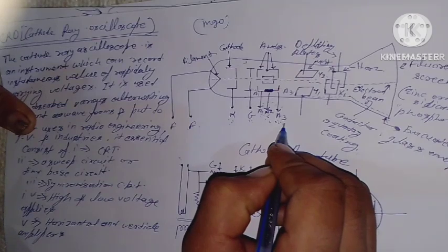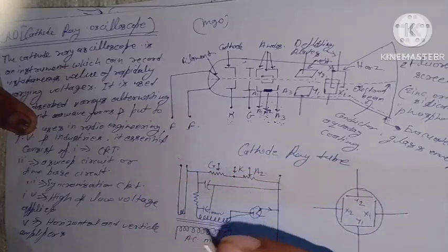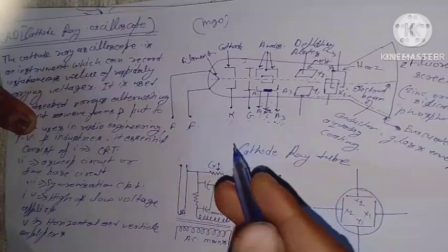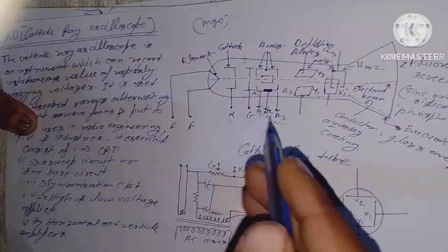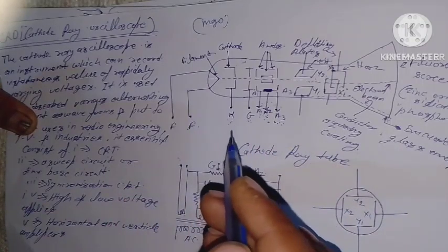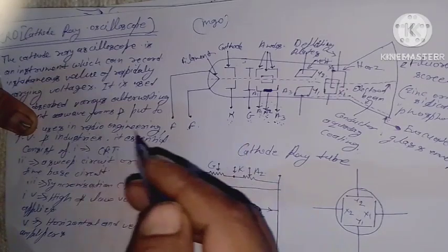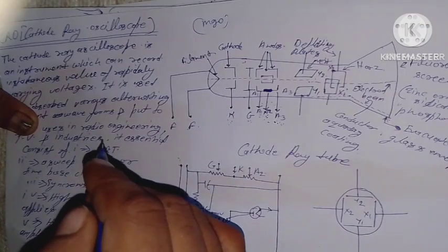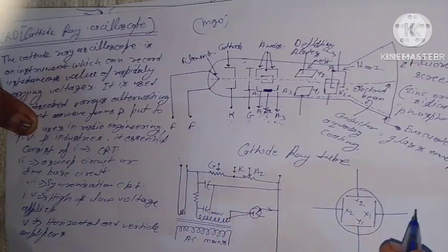The space through which the electron beam passes is free from all electrostatic or magnetic fields except those set up between the deflecting plates. As the electrons strike the screen, these leak off to the anode A3 and finally through the power supply to the cathode. The aquadag coating is necessary to remove the electrons striking the screen.